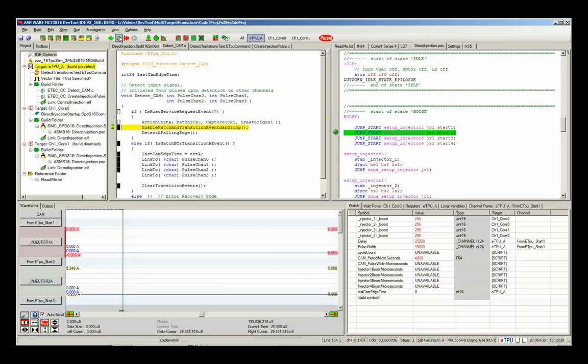The simulation stops in the eTPU code at about 20 simulated microseconds when it hits this breakpoint in the CAM code here, as indicated by this line of source code being highlighted yellow. Since a breakpoint in the eTPU causes simulation to halt, the eTPU target is automatically made the active target, as indicated by the eTPU target being highlighted in the project window and by the eTPU target's activation button being selected.